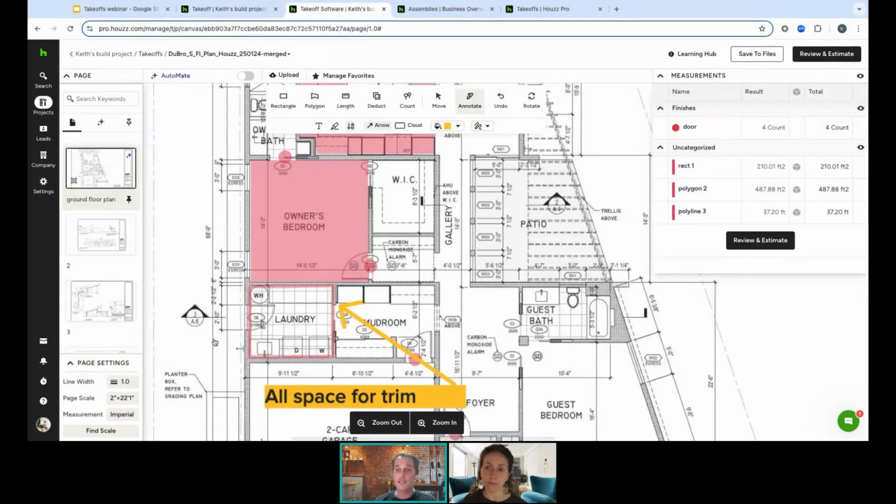And what you will definitely need to do is what I showed you for setting the scale. So you will need to set the scale on that. Just make sure that when you save the 3D floor plan, that you save it with the measurements on it, and there is an option in there on the 3D floor plan to do that, and then you'll be able to calibrate the 3D floor plan with the Takeoff tool.